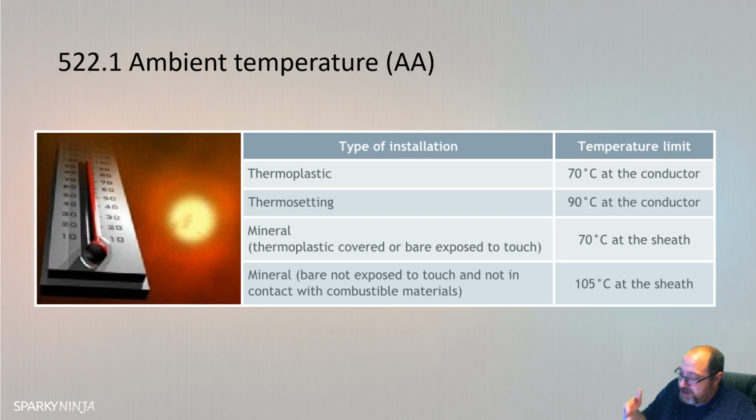So quick question then, what is the external influence category that is considered for ambient temperature AA as normal? Is it AA1, AA2, AA3 or AA4? Well, you go to the external influence category of ambient temperature AA, you look in the guidance AA1, AA2, AA3 and AA4, and only one of them is suggested as normal in the characteristics required section, and that's AA4. Now if you have trouble following that, then maybe go backwards and listen to how I found it, but otherwise let me know.